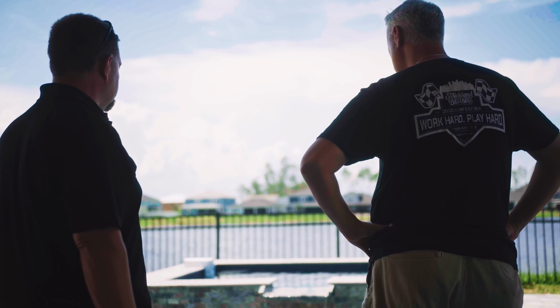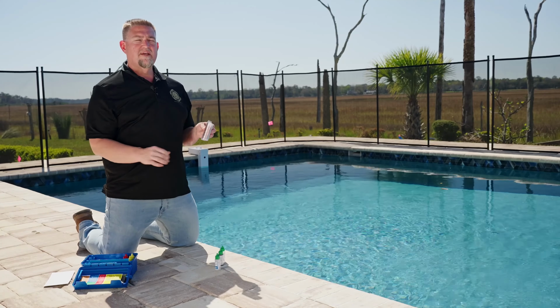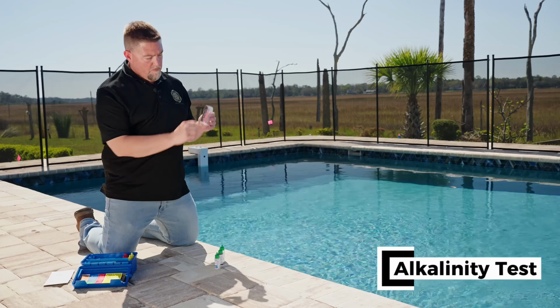All right, we're poolside testing our water chemicals. We're using a standard drop test chemical set. Using a parameter. The parameters down the side have measurements on them. So each chemical that we test is going to have a different fill level. First, we're going to test the alkalinity. 25 milliliters is where we want to go, which is this level right here.